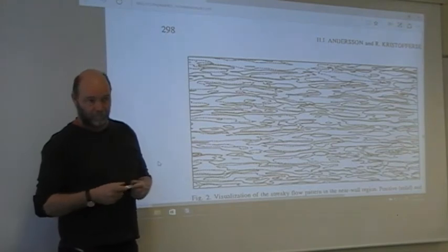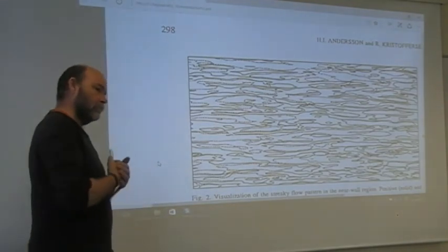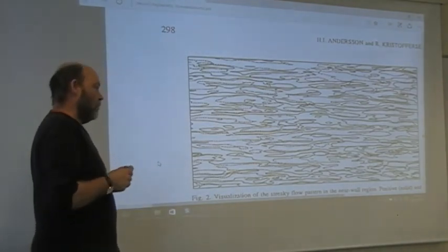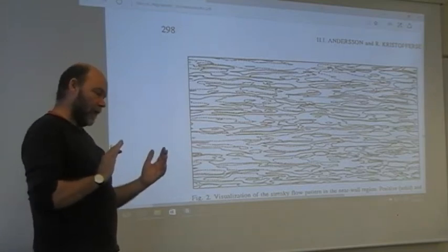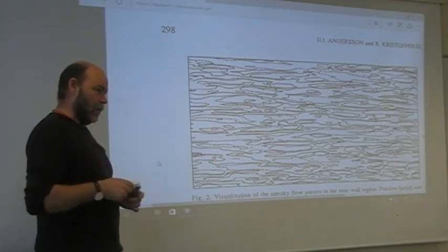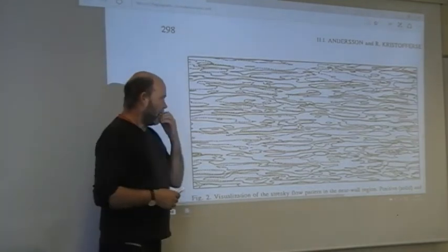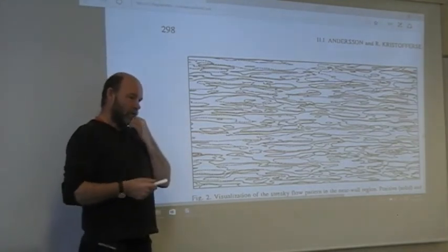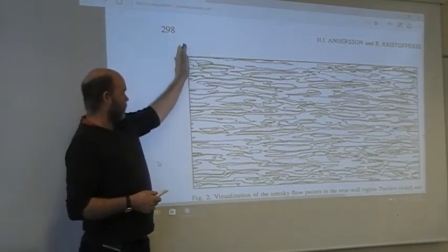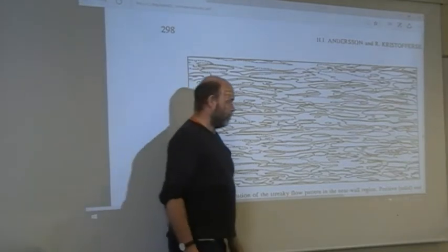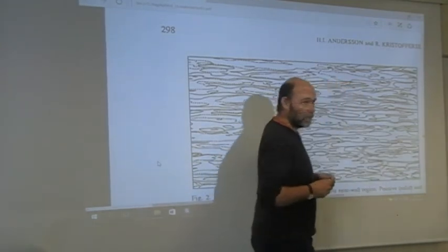And when you say you put up a driving force, you need some kind of pressure condition? Does that one also need to have fluctuations? No. Can you just do a pure? No, because you take your equation of motion, now the Navier-Stokes, not Reynolds averaged, and there you have a dp/dx, where one now might think, okay, that one should now be increased with a constant. What you can do is, of course, to say that the pressure here, P1, is then bigger than the pressure here, P2, because you have cyclic or periodic boundary conditions.